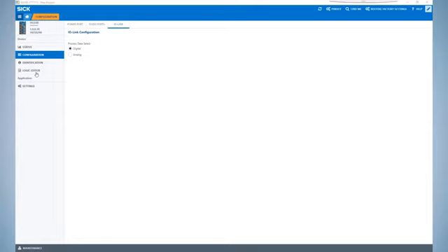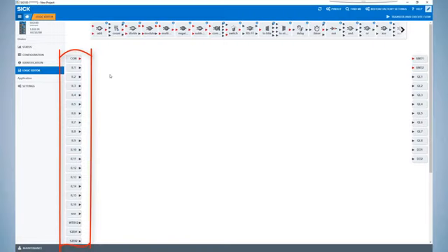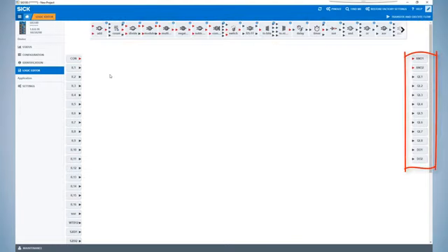The logic editor is a unique feature for the SIG100 that allows the user to create a simple system with the connected sensors or actuators by dragging and dropping logic blocks and connection lines. The left side of the screen lists all configured inputs, which aside from the physical inputs on the M12 ports, also contain those that may be coming from an IO-Link master via IO-Link process data. The upper middle bar contains the available logic gates that can be dragged down into the workspace. And on the right side are the configured outputs, which include those that may be sent to an IO-Link master via the IO-Link process data.